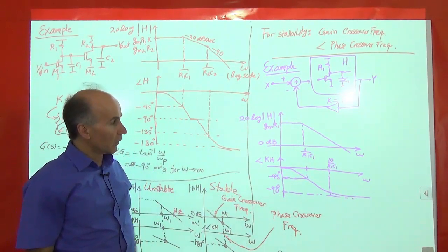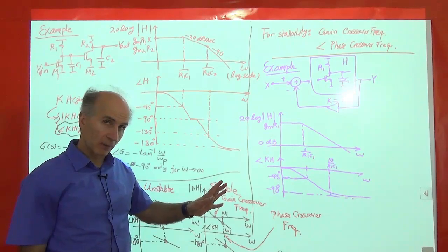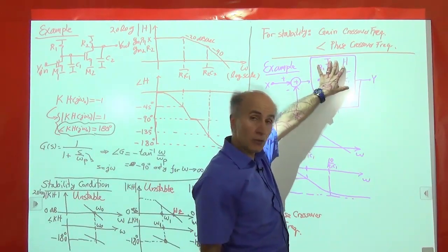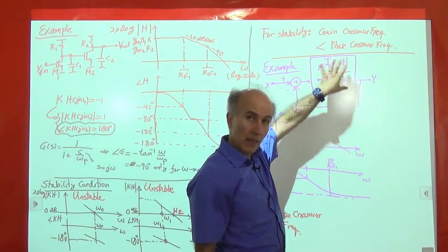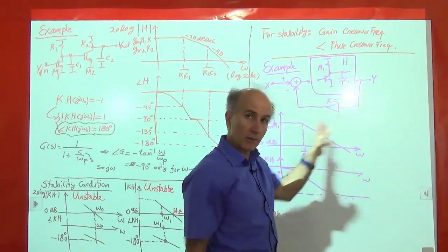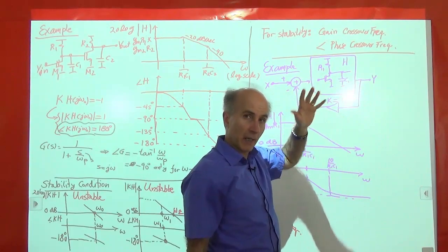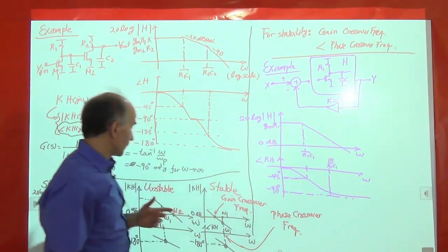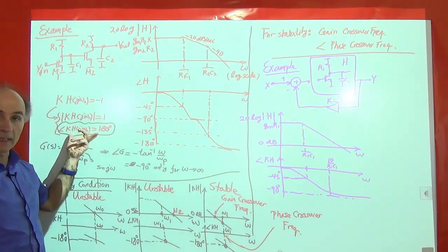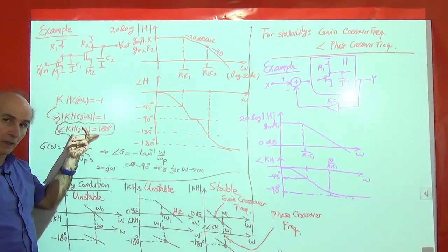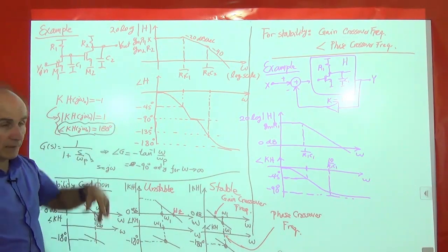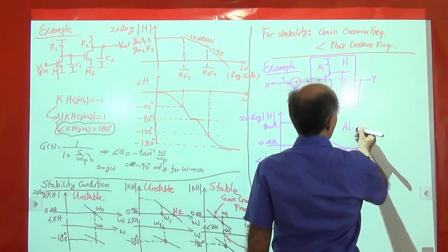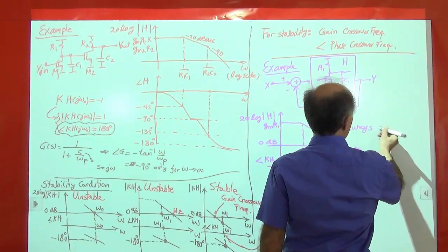Okay, so can the system become unstable? Meaning I have constructed this for H, K is 1, and now I place H into this negative feedback system, and I'm wondering if it becomes unstable. No, because this condition can never be met, right? We can never get it to a phase shift of 180 degrees. So that's always stable, right? So we say always stable.